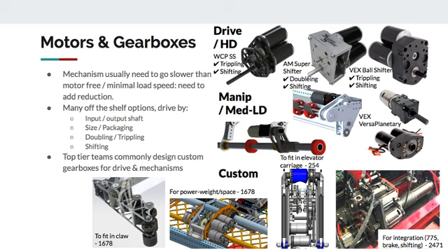Right. Okay. So I guess there probably is an adapter where you can go from 775 to like a super shifter or a ball shifter or whatever. But typically, if you get into the case where you want to take a 775 and put it into an environment where you want shifting or you want more than 2 motors, it very quickly gets into the realm of teams that design custom gearboxes. And so there's a couple of reasons why you might want to do this.